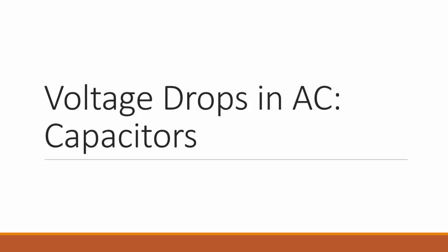If you wait a very long time, the capacitor will become fully charged. Therefore, it will stop any current, and there'll be some set amount of voltage drop across it. And it'll come out to be the EMF of the battery. And in the meantime, it'll exponentially decay up towards a set value, or rather, it follows that exponential rise curve. And then in the case where you discharge it, it decays down to 0.